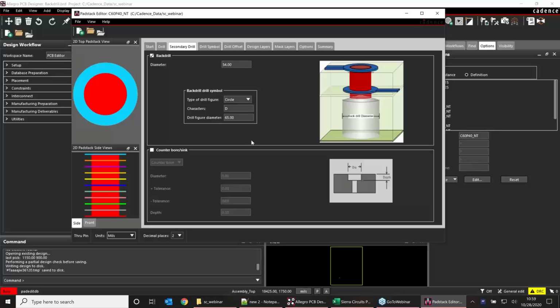There was also a question of when you back drill, how accurately can the back drill stop? The back drill can stop within 1 mil of where you want it to. If you're piercing through the copper and you don't want to hit the next copper layer, your dielectric material can be like 4 mils, no problem, and the back drill can stop. But the back drill itself should be bigger than the original hole size so you can properly clear out that copper.